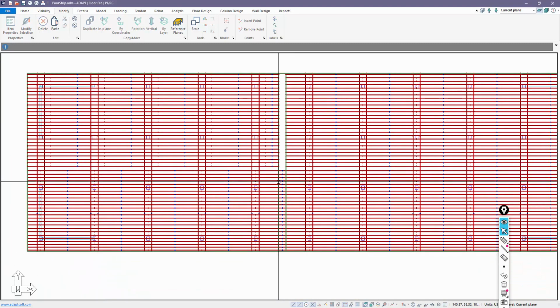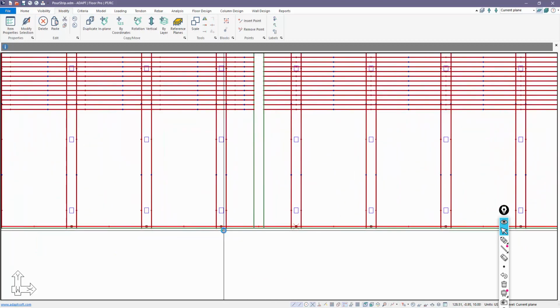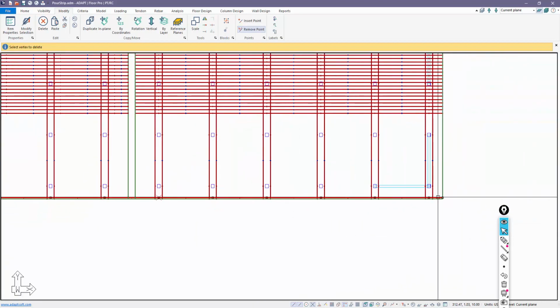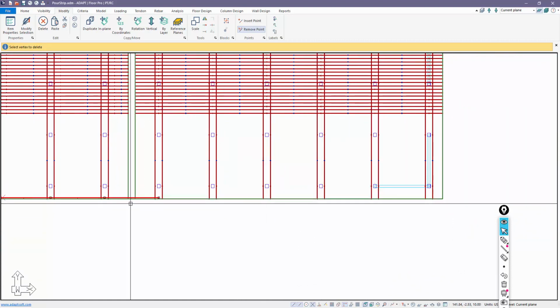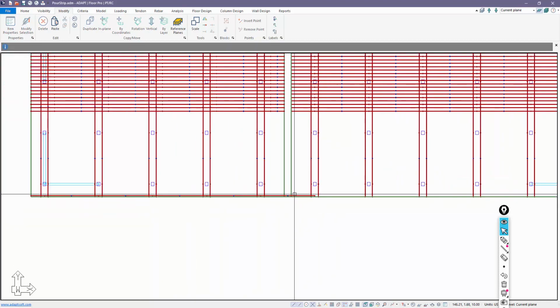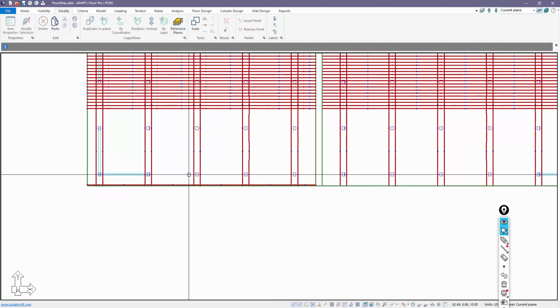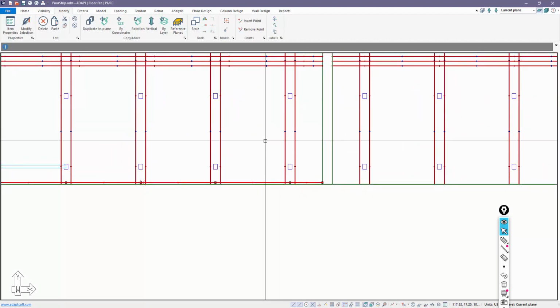Now, if we were to model this, obviously we would just simply model one side, copy down, model the other side, copy down. So that's what we'll show now. This is similar in nature to what we did previously, but rather than actually modeling this, I'm just going to modify this first one. Again, I'll come back and delete some points. There's my first. I'm not going to change that end span, but there's the first tendon. Now I can copy that vertically.